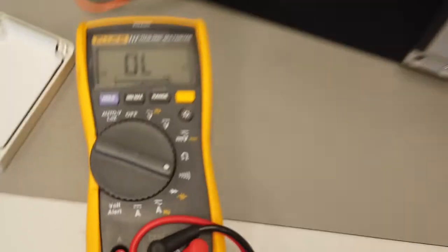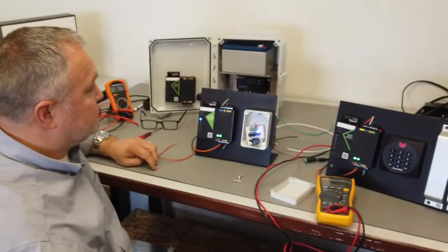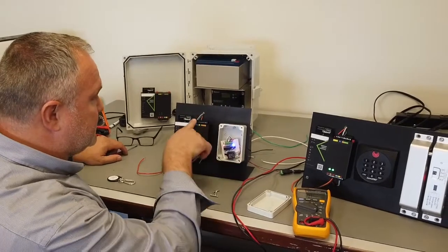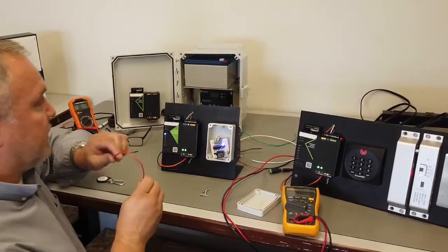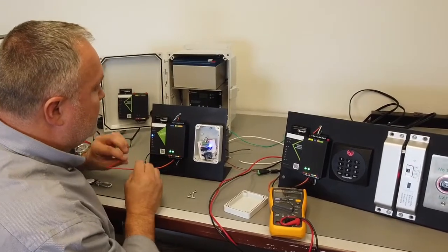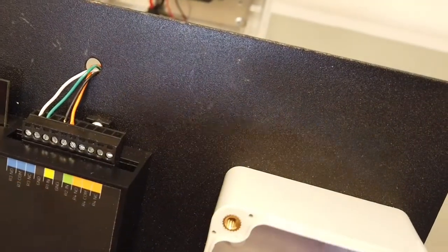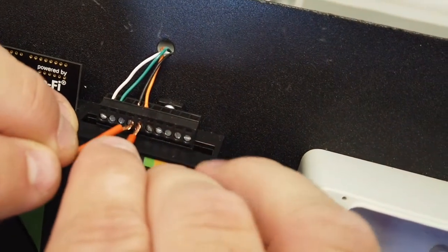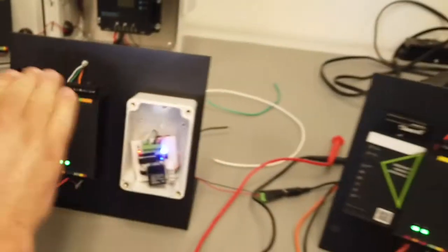All right, now if we are not getting a gate closed or a door open or whatever the relay is supposed to do, well then what do we do? Obviously you can check for continuity from here to here, or you can also just check that the relay is actually triggering using a jumper wire. Okay, so if we trigger this relay here, in this case we're connected into yellow and ground, R1, I'm jumpering it, and it is triggering the relay. So we know that there may be something wrong with this situation.